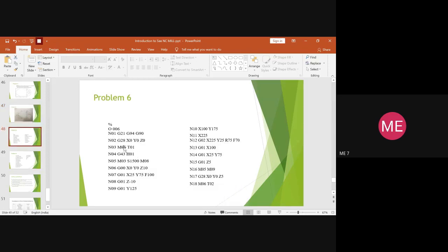And later the tool which you have selected should be compensated, right? So you have to go for tool compensation, which is G43 for the offset number 1. So this offset number is assigned with the tool compensation so that the tool length is adjusted as per the requirement with respect to the data which is available in the control memory, and hence this step will be common.